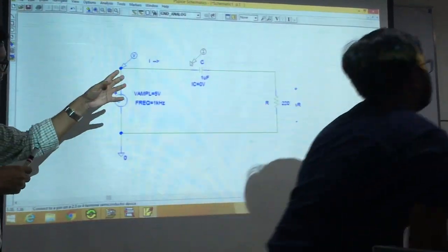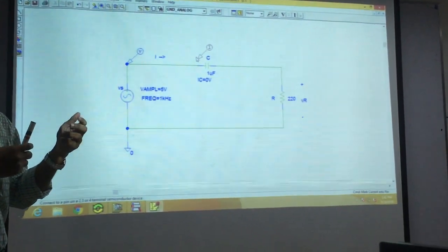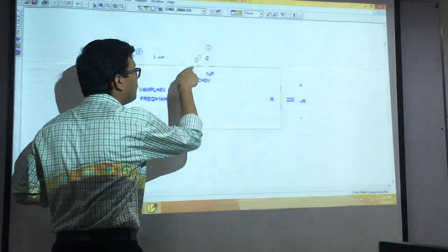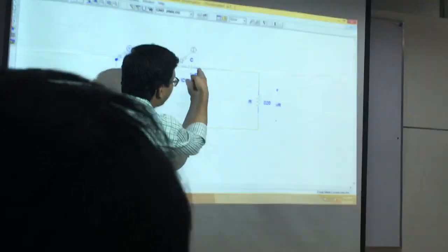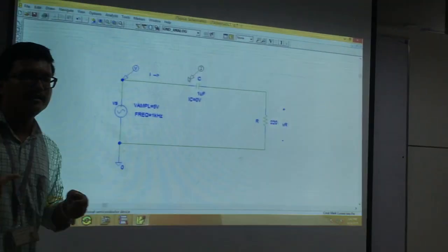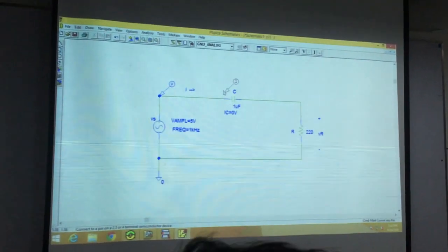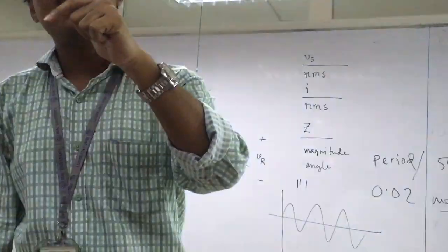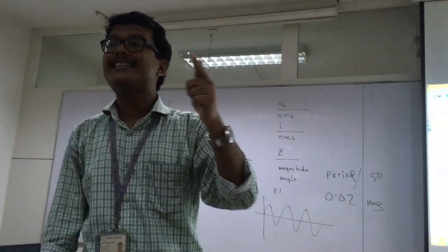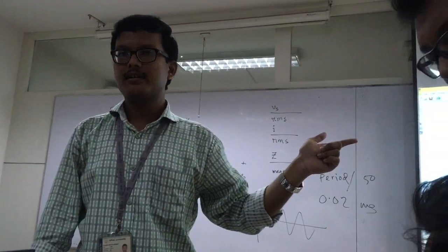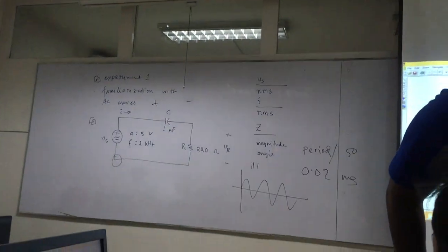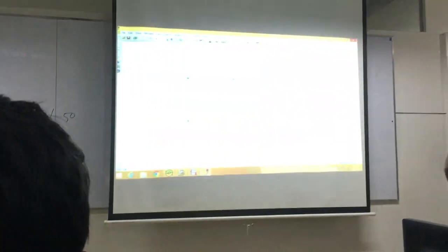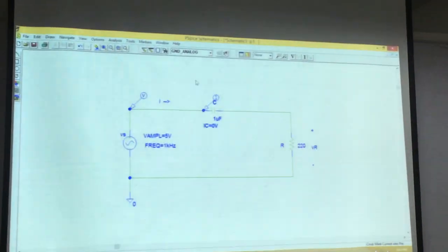But then again, putting it has got a connection with the direction of the current. For example, if you put it here, then the direction is going to be this way. If you put it there, the direction is going to be this way. Why? Because that marker finds out the current which is getting in through the terminal where it is placed. Okay? That's the definition. So that's why we're going to put it somewhere here. There. The direction is this way. Okay?